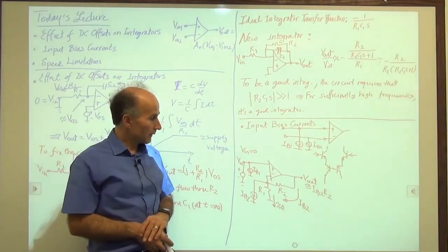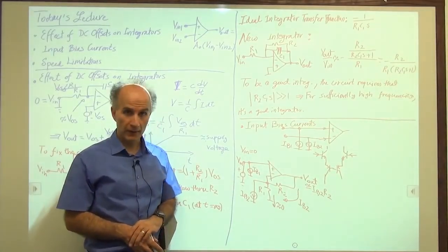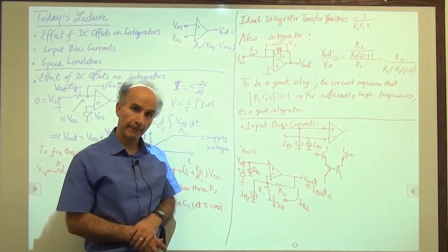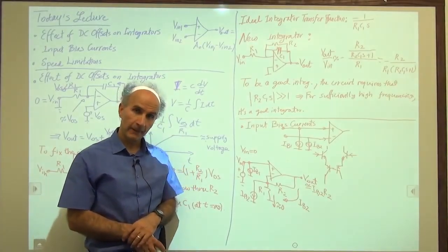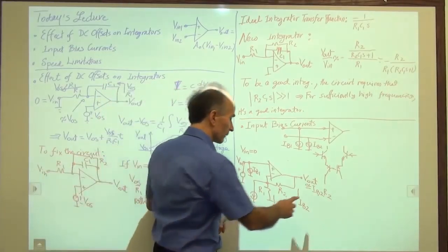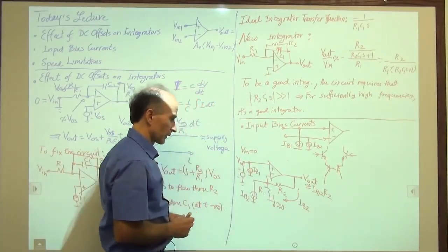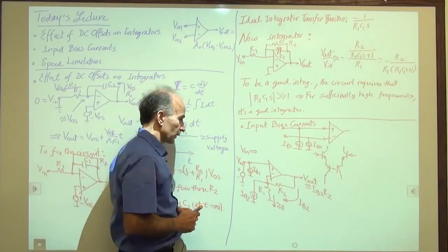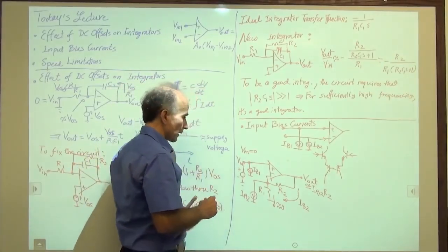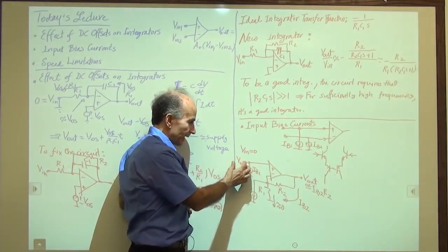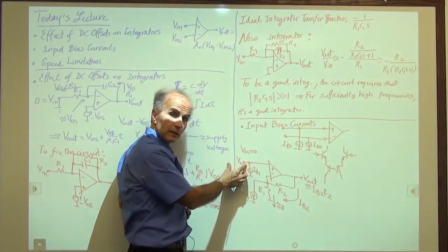All right, now it turns out that there's a quick fix for this so that this error is removed. So what I'm thinking is this. I have a certain amount of voltage here, IB2 times R2. So what if I try to come from outside and add a little voltage source here?